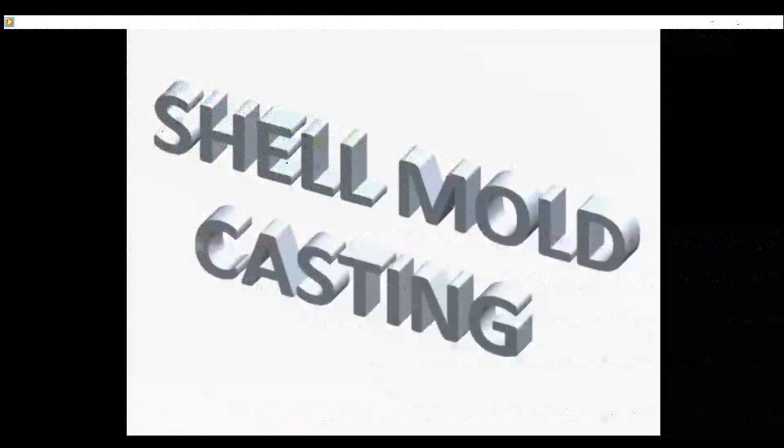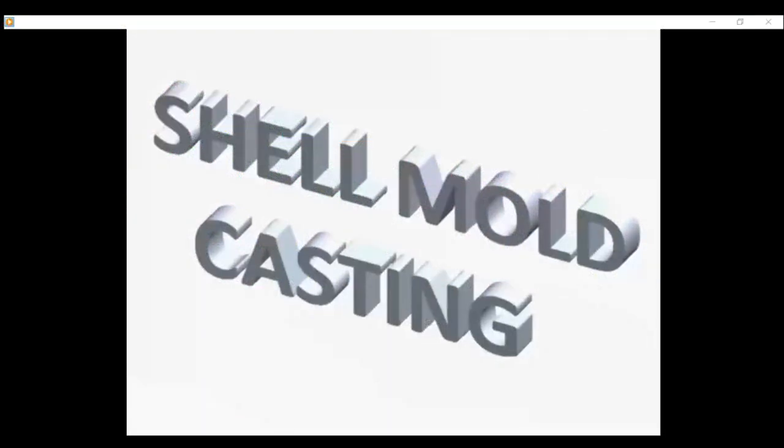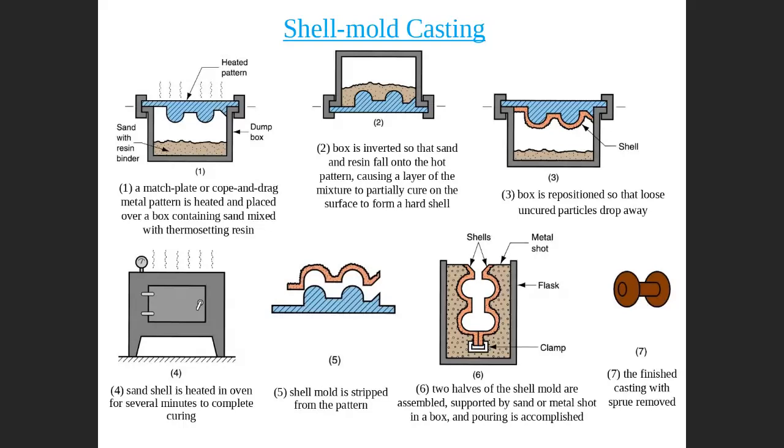Get back again to the slides. So this is the shell mold. Again, shell mold. You heat the pattern or shell, and then you invert it. Then this one will totally cover. Then you leave it for a while, and then invert it again. Then a layer will stick to the pattern. You take this one and put it in a furnace, both together. When the shell becomes hard, you take the shell out and do assembly here, and you cover here. You put sand here, and then you put liquid inside. Liquid will fill this. Later you destroy it, you take the part out. This is a shell mold.